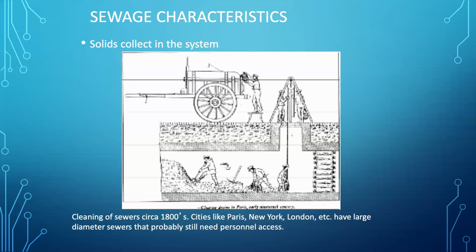And so one of the principles of sewer design is to be sure that the flow velocities are high enough that the solids keep being transported over time, but low enough that that solids-laden water doesn't become essentially a liquid sandpaper. And so that's kind of the synthesis of the 2 to 10 foot per second design flow velocity.